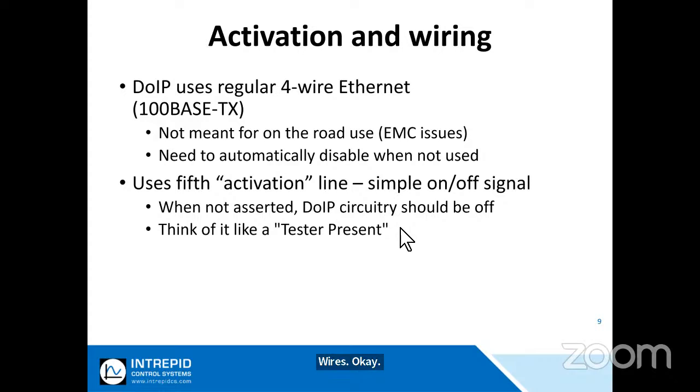That's something that in industry, I'll show you at least one trick that they usually use for an Ethernet cable to connect between a laptop and the vehicle. But basically, the activation line just assures that you don't have an Ethernet port that's just out there hanging in the breeze that you could hook up to and do whatever you'd like. You have to at least assert the activation line. Now, we'll talk more about how insecure or secure that Ethernet port can be later on in the presentation.